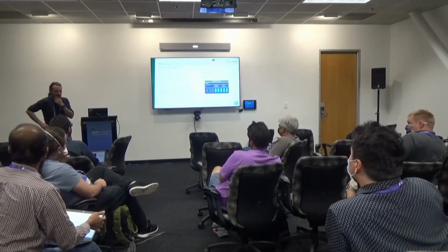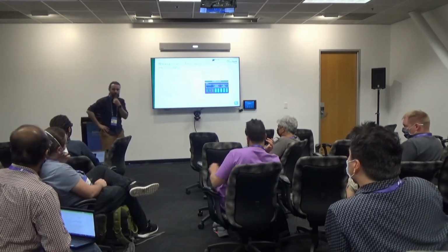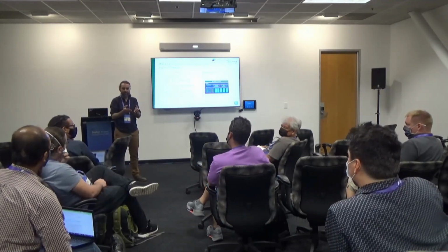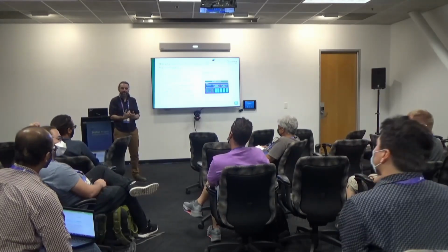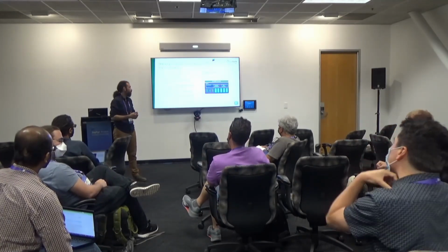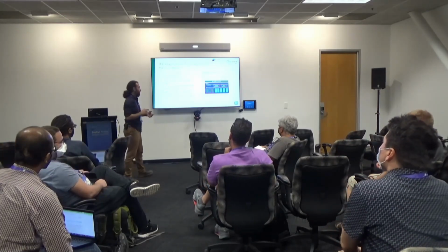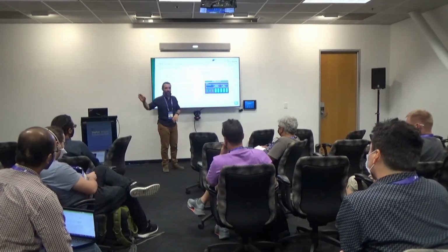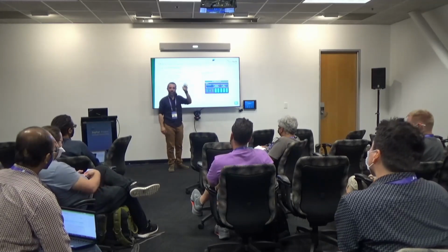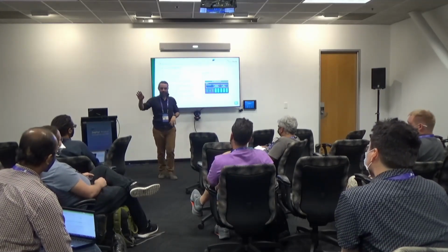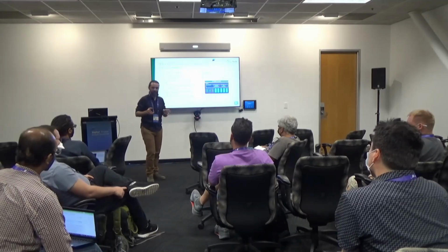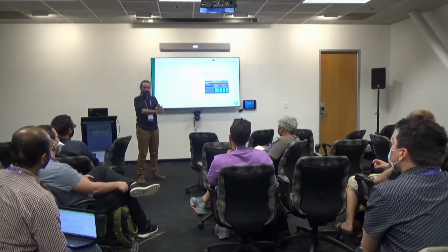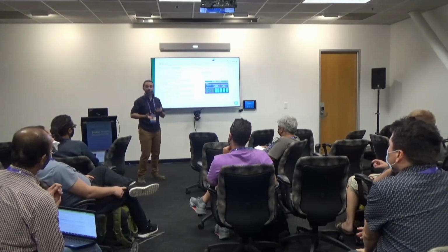Platform IO is an add-on to VS Code that allows you to flash code to a microcontroller. At least that's how I understand it. It goes way beyond that, but that's one of the main functionalities that I found in it. And Platform IO is also a very good way of saying, I wrote this library and I put it in this GitLab. You give it to Platform IO, I say I'm using STM32 or whatever other type of platform to flash, and Platform IO is going to magically parse all that information, download everything you said it should download and compile all that stuff together. So it does a lot of package management for you.